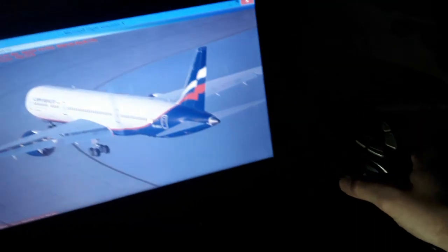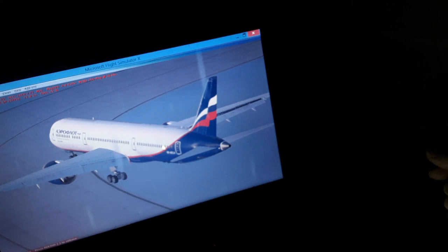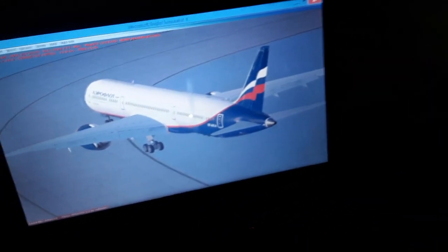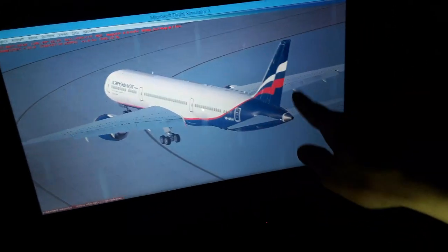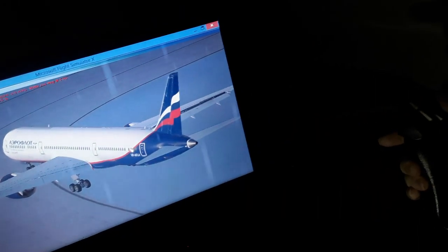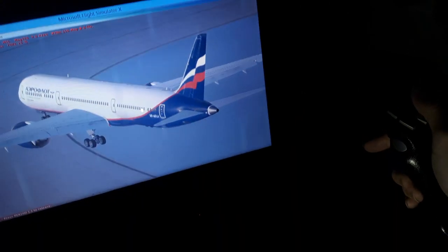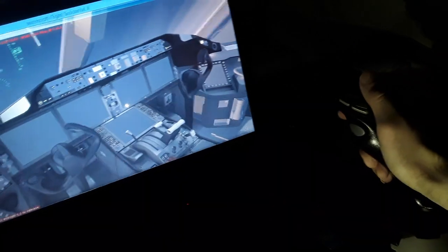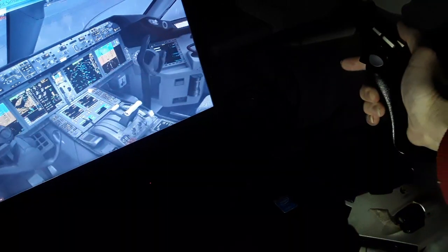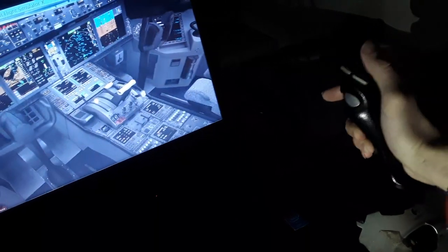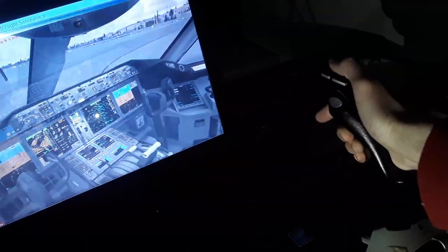Same thing, you use the side stick left and right, ailerons and spoilers, to make left and right turns using the wings, left and right wing differential lift when you move the wings up and down. Ailerons and spoilers, side stick left and right in the Airbus. Also control wheel left and right in the Boeing, to make left and right turns, deflections. So this is the explanation.